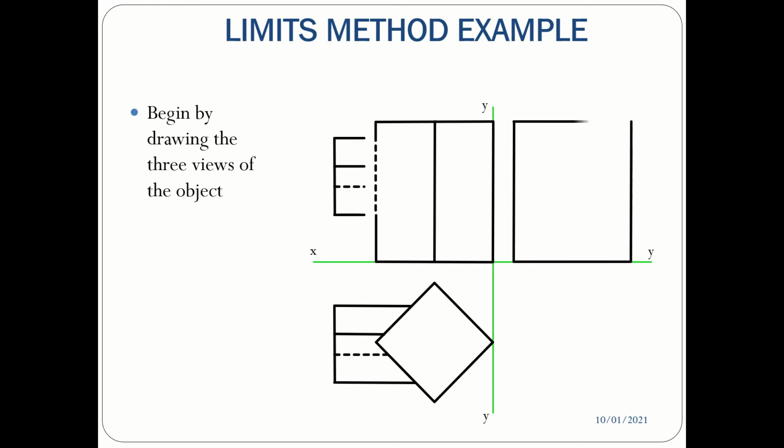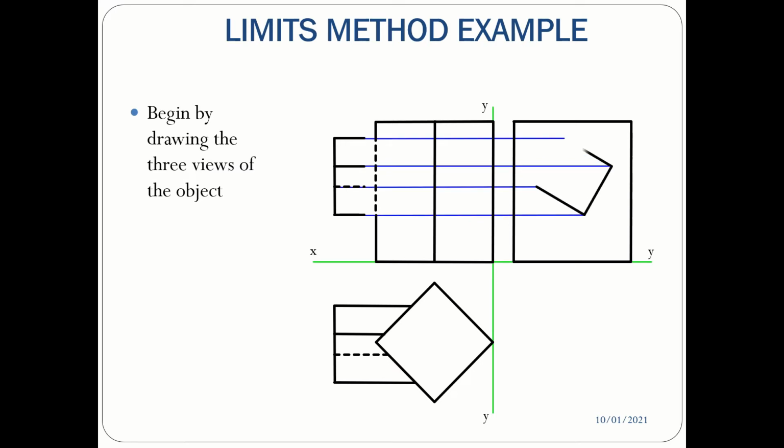And if I was doing that, I would draw the bigger body first, and then I would bring across our height lines there, and I would set up the end view of that square. Now, what's very important in doing that is that you recognize which line is which in each view. So this square-based prism has four corners, 1, 2, 3, 4. But you need to be able to identify which ones in elevation are the ones in plan.